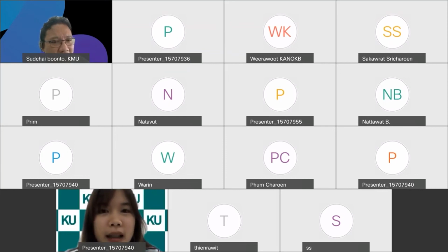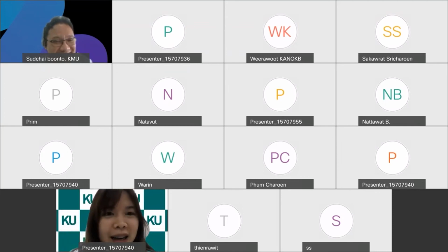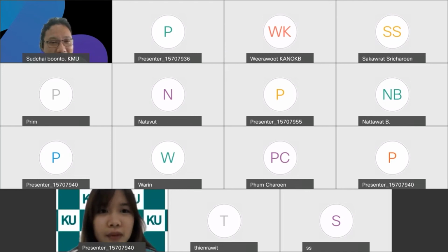I think it may be the processing time for sending data: after the sensor reads and the robot is commanded to stop, since the distance is very short, the command may not arrive in time for the robot to stop. Okay, you mean the sampling time for the robot is not fast enough to stop before the set point, and this happened because the distance is too short, right? Yes, like that. Okay, the time is up.